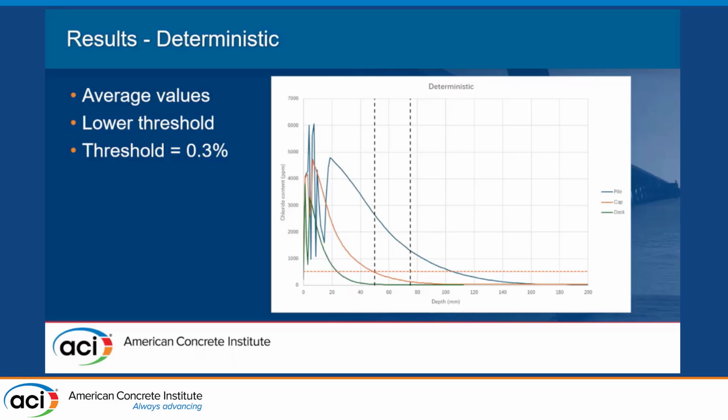So you see the green curve here is for the deck. The intersection between the chloride content profile and the corrosion initiation threshold occurs at 75 years, and we're not even close to the cover of 50 millimeters. So yes, we may have corrosion initiation, but for bars that would be below about 22, 25 millimeters from the surface.